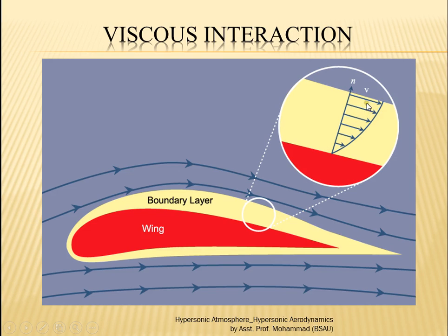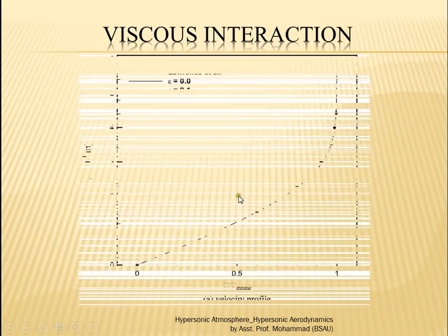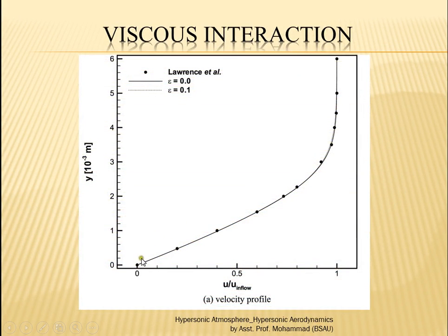Definitely, we just discussed that the interactions of the boundary layer with the thin shock layer and the entropy layer also affect the velocity. But in the normal case, the velocity at the outer edge of the boundary layer is the velocity of the free stream flow. So by keeping those two earlier discussions aside, we are just trying to discuss what happens in the case of the boundary layer, which is actually a viscous phenomenon. In this viscous flow, the velocity varies from 0 to the maximum velocity.